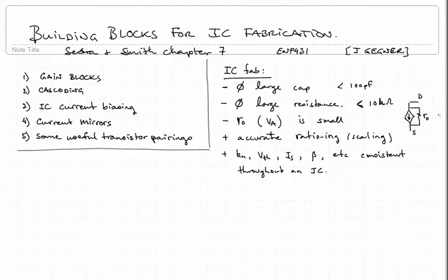In addition, some of the parameters of the devices, such as transconductance coefficient, threshold voltage, scaling current, and forward current gain, etc., if it was bipolar transistors, can be well matched on a given die. It's not that we can specify them with great accuracy, but from device to device, they will be consistent on a given silicon die.